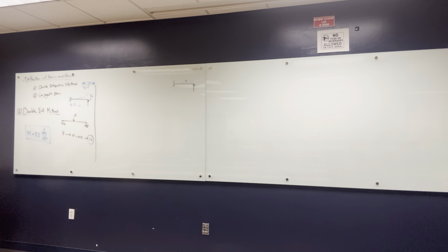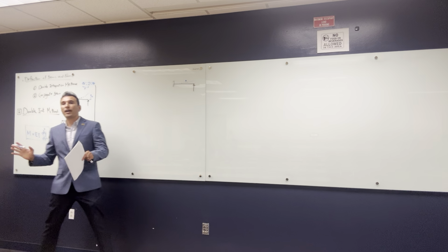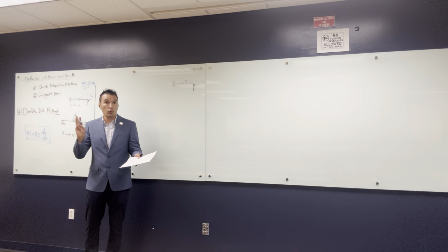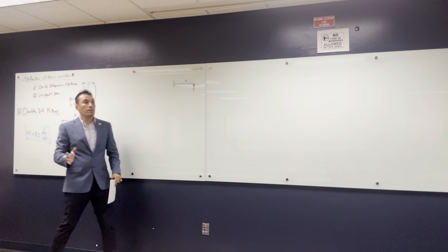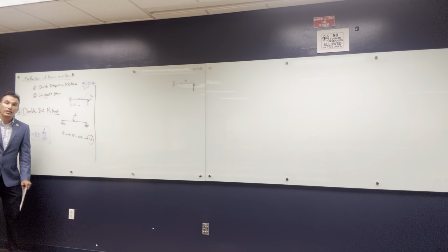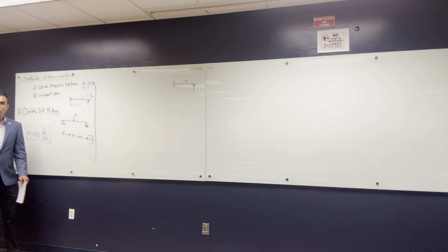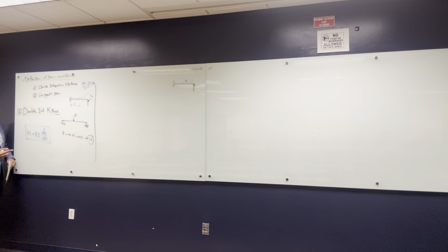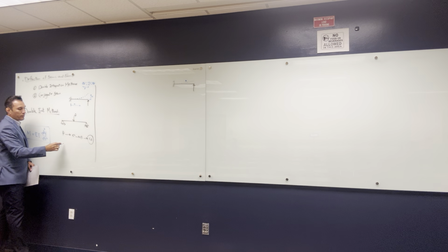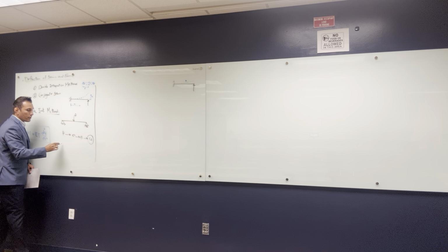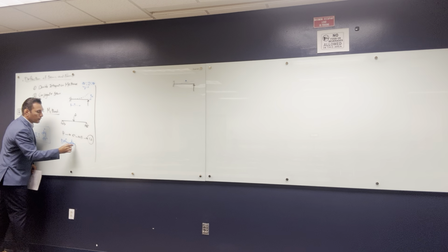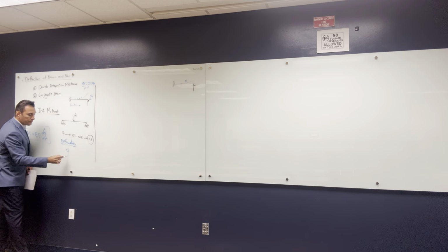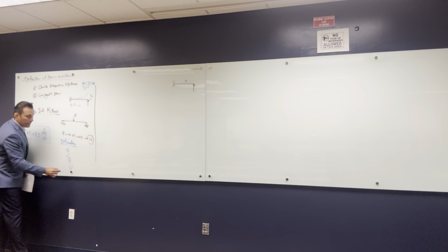So there are three components related to deformations, the same way that we have components related to internal forces like normal, shear, moment, and maybe torsion. Torsion is a type of moment. So we have these internal forces. Also the deformation, not the deflection, the deformation, we can describe with three different types: y, theta, and the curvature.